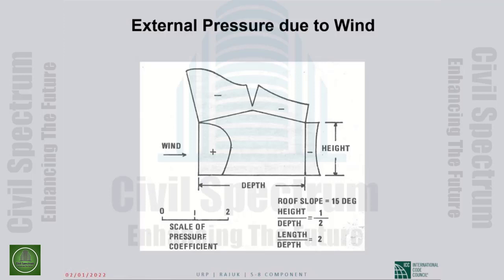After hurricanes, I really with my own eyes have seen whole buildings uprooted, sucked up from where they were, and deposited several hundred yards away. That's because the anchor bolts are flimsy or non-existent. The bolts that anchored the building to the foundation.